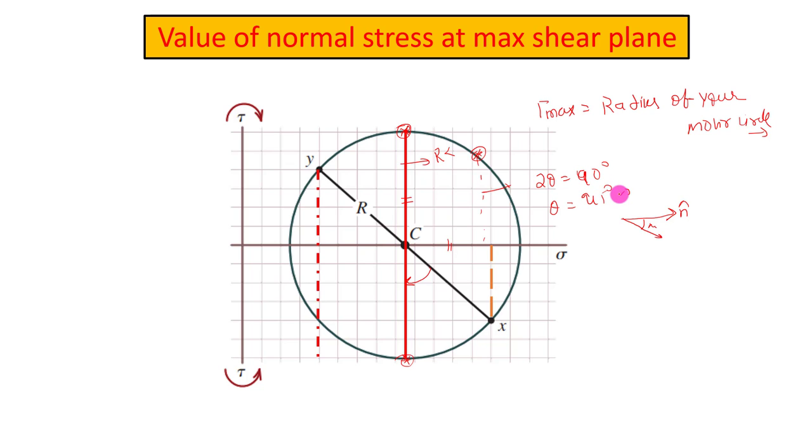So the maximum shear planes and the principal stress planes always make a 45-degree angle between each other. It's directly clear from the Mohr circle without going into all the derivations. That's why the Mohr circle is such a beautiful concept: just by looking at it and using some geometrical and trigonometric relations, you can come up with any of the equations that we had derived using mathematical formulations.